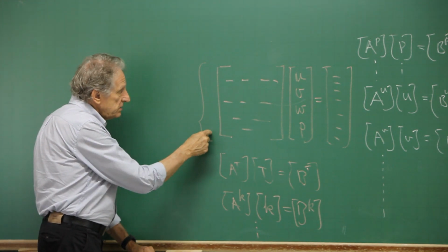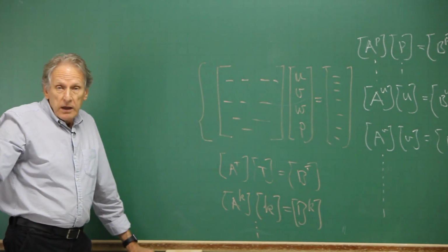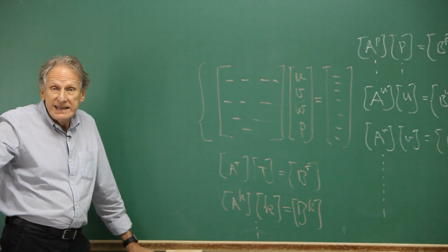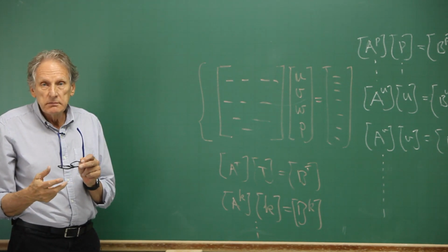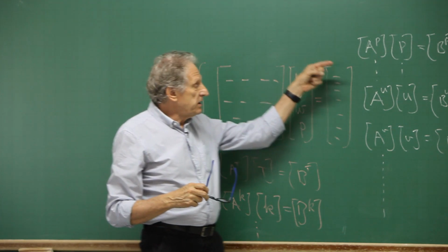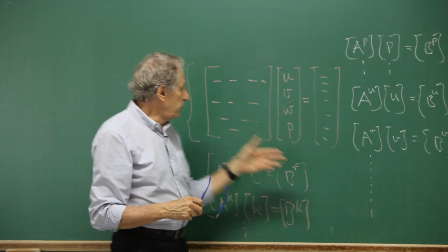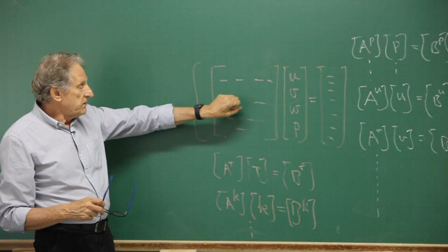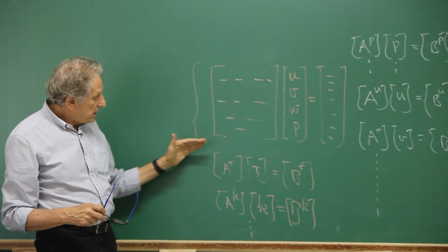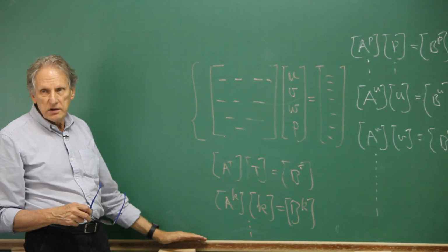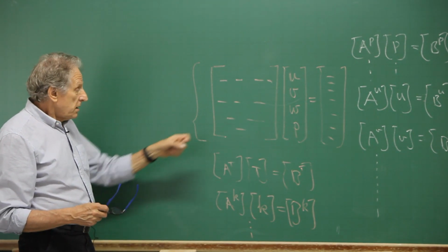We solve simultaneously U, V, W, and P, because when you do that, you get rid of the need of pressure velocity coupling because you are already coupling. You need some kind of coupling here between pressure and velocity because you're solving segregated. When you solve here, pressure and velocity are already coupled in the linear system. And then the other scalars, you solve one by one. You go back and forth, iterating.